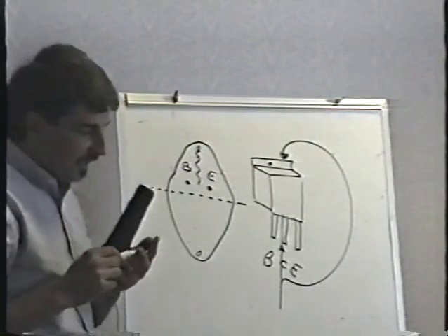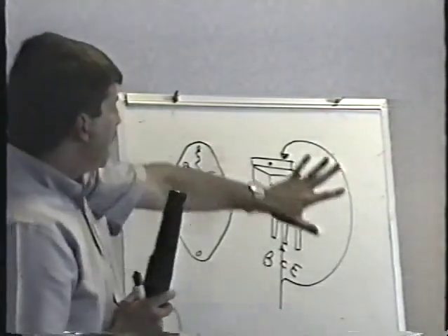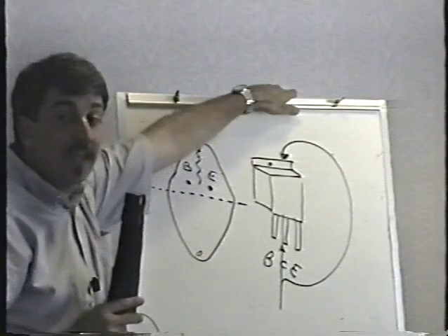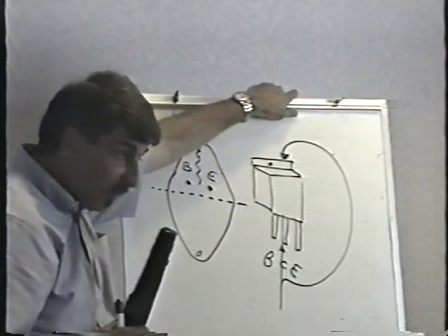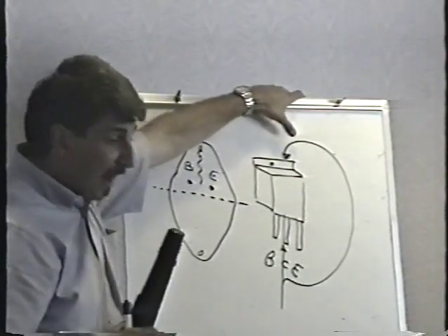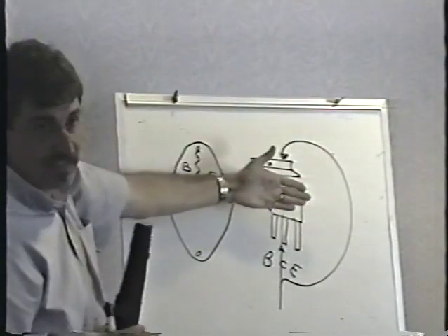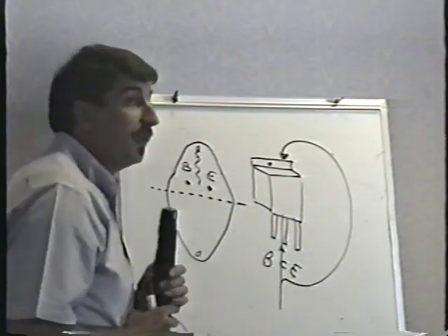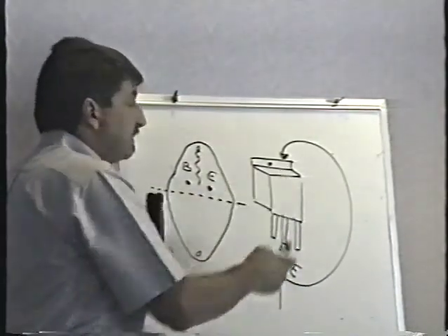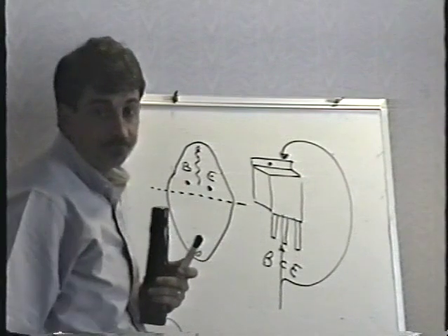These are electrically the same point, meaning the metal tab is electrically active. It is the collector as well. And again, when we open up our power supplies, you'll see that there's a small insulator behind these transistors as well.